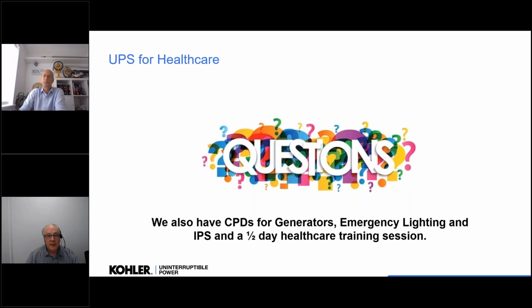Thank you. Just looking ahead, another attendee's asked, do you see fuel cells replacing batteries and generators for UPS in the future? Yeah, there's a lot of work around fuel cells and large batteries to back up for generators. At the moment, it's not there, but obviously there is a lot of work around hydrogen. But there's a lot of problems to overcome with production of green hydrogen, with storage of hydrogen, and it's not necessarily going to be a good thing for backup.